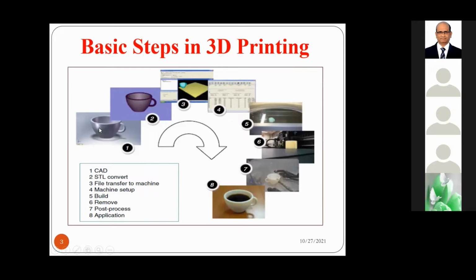First, you have to develop a CAD model, whatever model the function requires. Then you convert it to an STL file. That STL file you open in your 3D printing slicing software. Nowadays each 3D printer provides its own software, but almost all the basic operations are the same. The features differ, with some small differences, but the process is the same.